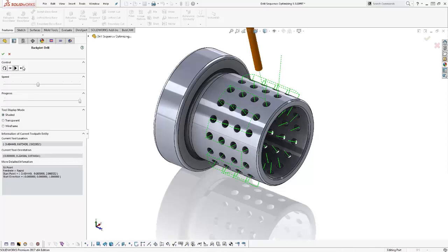Okay, so the drill sequencing options in review, again, you have 5 sorting options that you can use. You have control over your start location, which corner it starts from. You have reverse each operation to optimize your drilling, so you remove that link back move to the beginning, and it is supported in wrapping groups. It's supported for your cross drilling, face drilling, and your multi-axis drilling. Okay, so that is our first new feature of BobCAM V6.